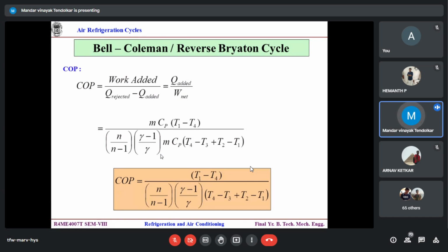So this is another classical way to resemble this to the Carnot cycle. COP of a Carnot cycle can be expressed in terms of temperatures alone. Here also the same thing. And the moment you execute even the isentropic process, even this bracket also is cancelled. There are purely temperature terms. So this is how it resembles very, very closely to the Carnot cycle's COP.